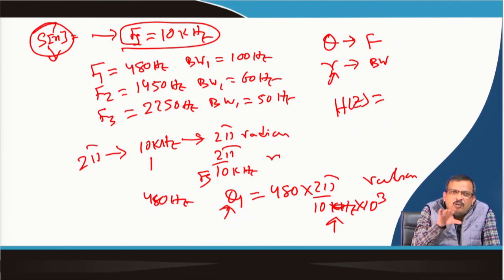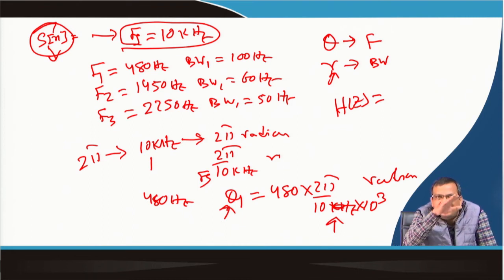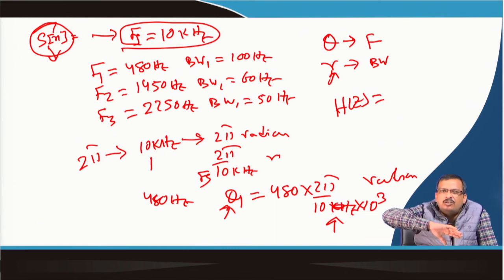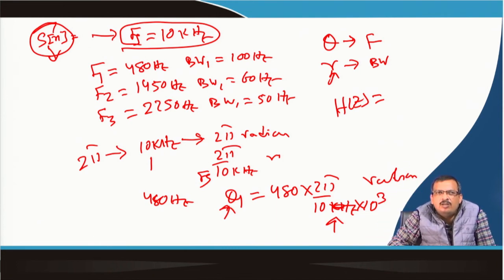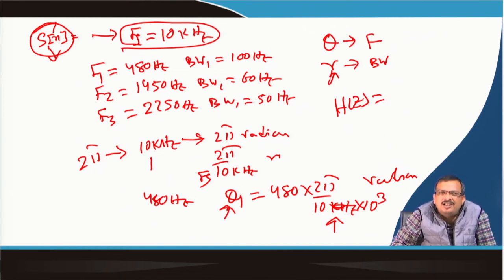If the poles are within the unit circle, the oscillation will die down or decay. If the poles are outside the unit circle, the oscillation gradually grows. So, from the Z transform I can find out the stability of the system also. If the system is to be stable, all poles must be inside the unit circle. Unit circle means Rk is equal to 1.